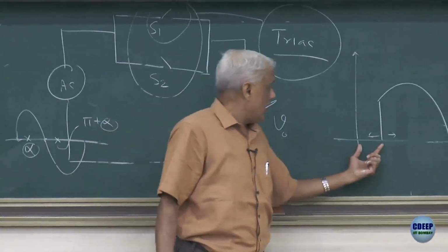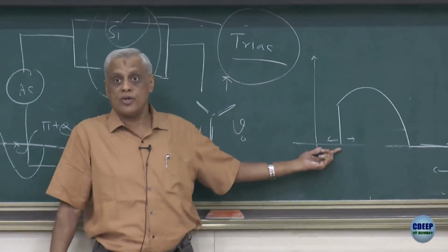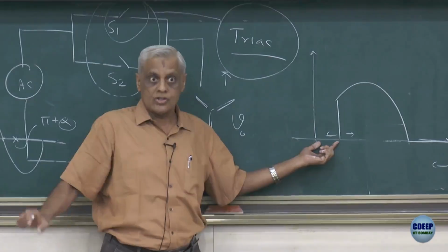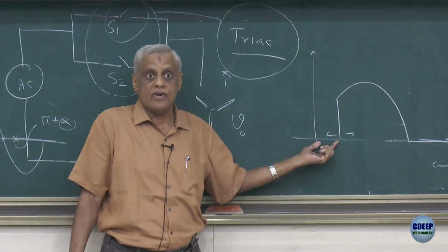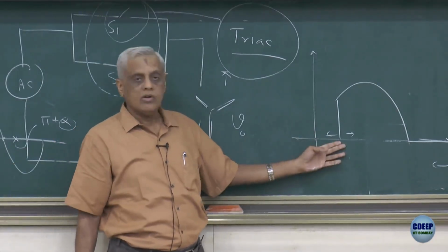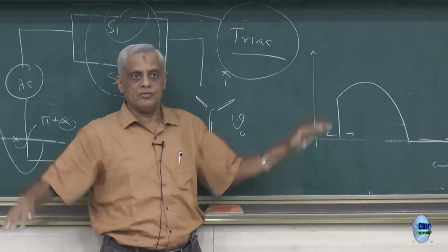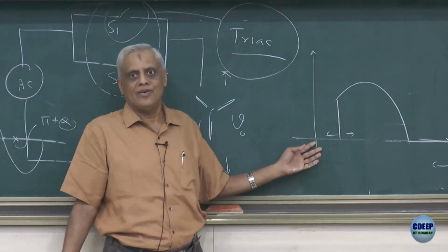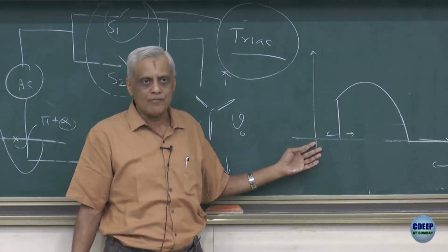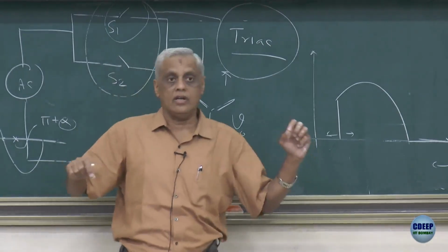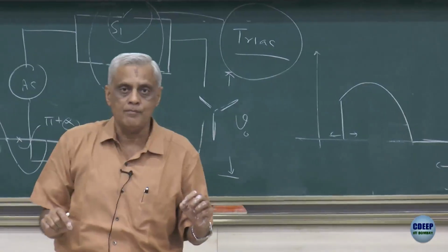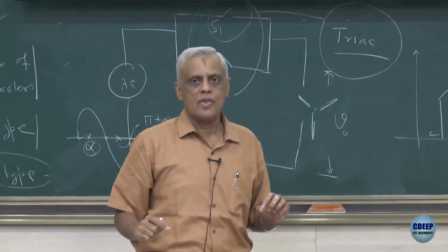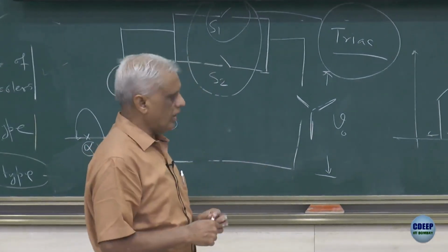Now the thing is, this is unlike the voltage or potential divider system, the original bulky regulators which will get very hot, because now you don't have any flow of power through a resistive path. So there is no loss, unlike the voltage divider system. So you must do one thing, just try to see the voltage divider system and say why I am saying it is lossy. Just try to verify that part.